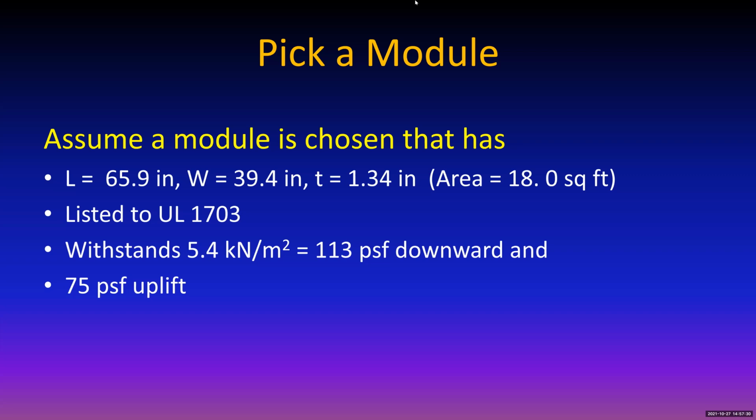There's sort of a basic standard, like UL 1741 is a basic, you have to at least be this good. Other manufacturers take pride in being better than that. Certain manufacturers take pride in manufacturing a module that is adequate for use in the 175-mile-an-hour high velocity hurricane zone in South Florida, the Miami area, for example, or out in the islands.